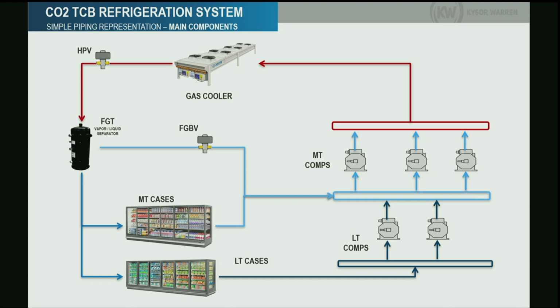We have the flash gas tank. We have another valve here that we call the flash gas bypass. And then you have your medium temperature and low temperature cases. Those cases will have similar components to what you have with HFC, either with case controllers with the electronic expansion valve. All of that doesn't change. It will change only the refrigerant that we are running.